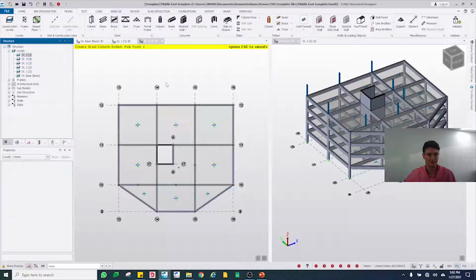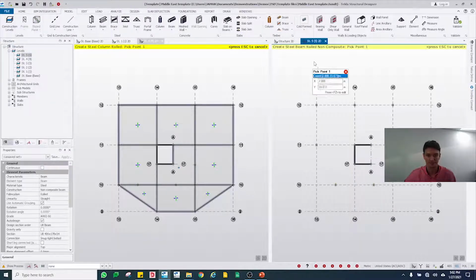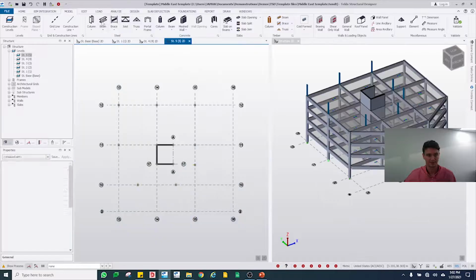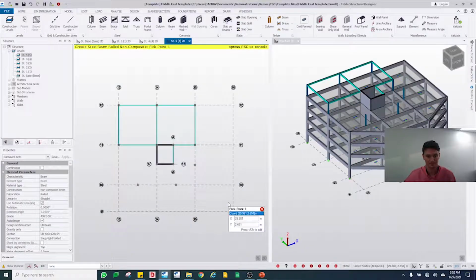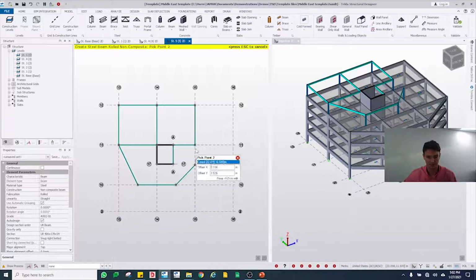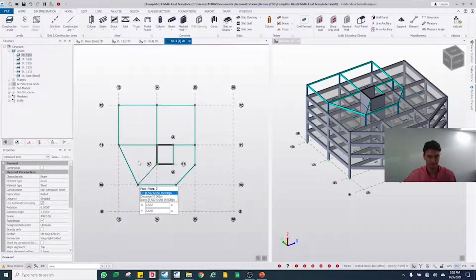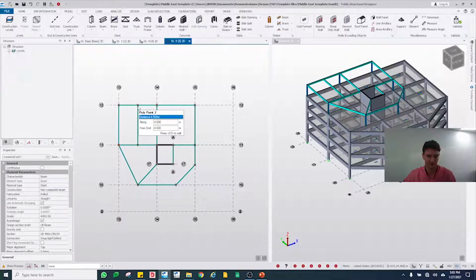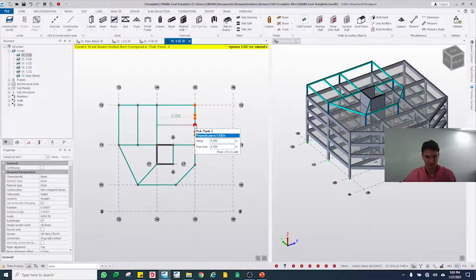Similar to the previous approach, I can add some steel beams. I can just move this here, so I can add some steel beams on the roof. And again, it'll draw them between grid lines along supports. If there's no grid line, I can just connect the dots, like so. If I hover over a member, you'll see it snaps to certain locations, like half points, third points, quarter points. If I press F2, it gives me different distances along the beam to draw in.